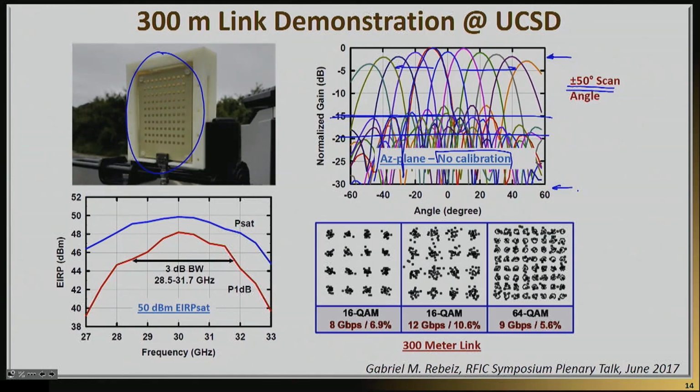But if you do the calibration, and in some applications you do need that, for example, in satellite comm, we often have to get the side lobe down to the 30 dB level because we can't radiate somebody with too much power, then you actually do need a calibration and get this thing done. But in most applications, I would say the side lobe level in the order of 20 dB is more than acceptable. And that shows really the promise of having these things potentially work uncalibrated.